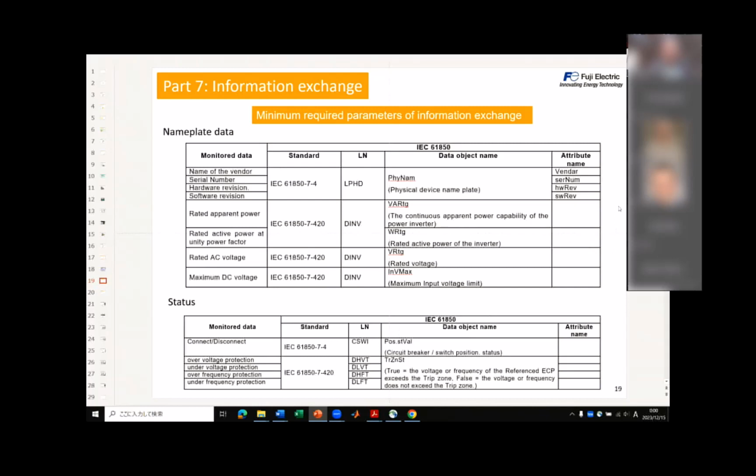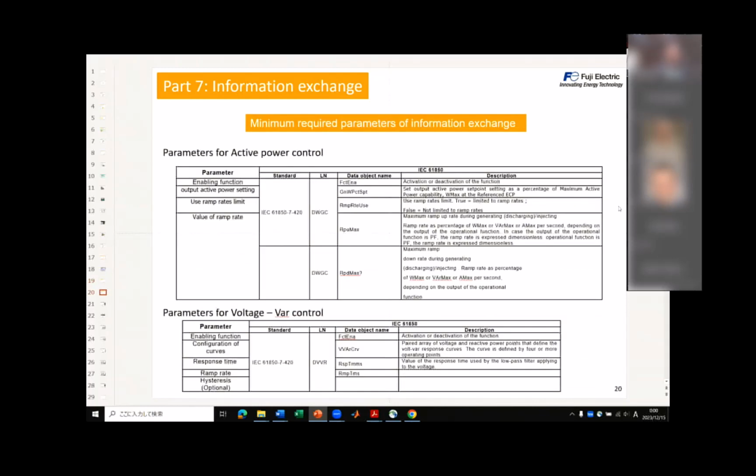Today, we will demonstrate the constant power control and the remote configuration. Here is one of the examples. In the PCE, we have already programmed such an information model as the parameters. So active power control can be managed with those parameters. Also, internally, the volt-var control can be reconfigured by changing those parameters.